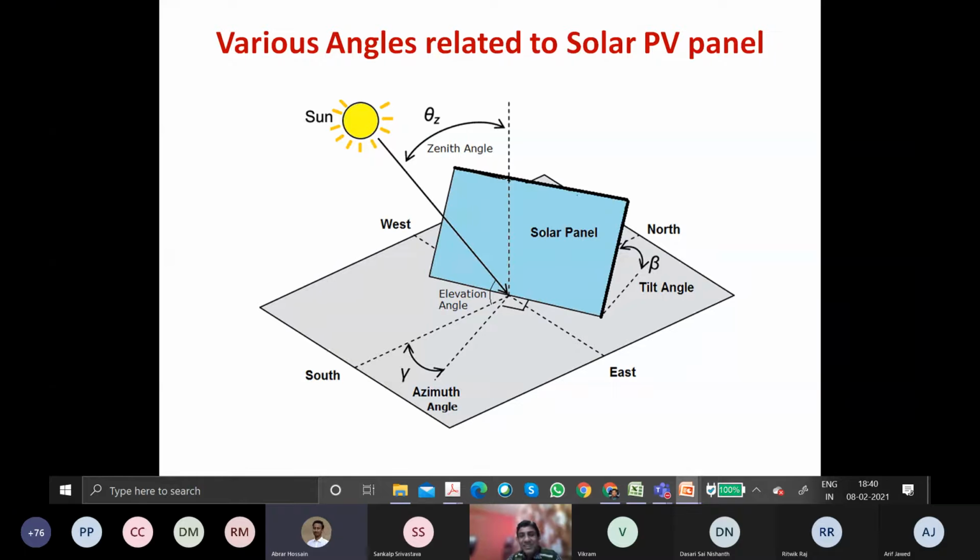Did you understand my question? Your answer is the opposite. I have three materials A, B, C. Material A has a band gap energy of 1.5, B has 1.3, C has 1 electron volt. Light is falling from the top. Which one will you put at the top: A, B, C or C, B, A? Sir, with 1.5 electron volt on top.